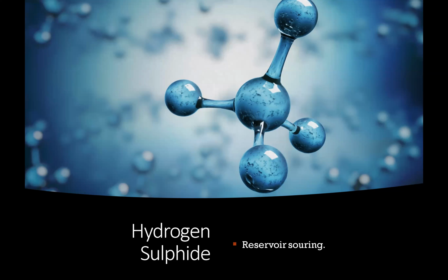Okay, thank you. The next question from Wendy: what is the difference between water cut and water holdup? Water holdup is a parameter calculated when we have production logging. The water cut is a water sample taken from inside the wellbore or from the surface, where there is a sampling point.